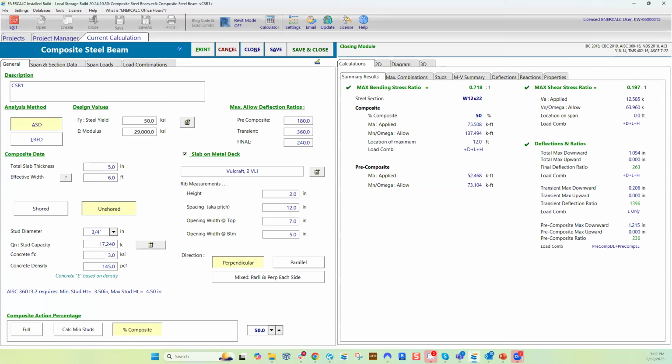All right. Question from Mark. Does the auto-calculated pre-composite slab weight include extra weight to account for the pre-composite deflection? No. Any additional concrete required to deal with ponding effects or the deflection would need to be accounted for as an additional pre-composite load. So the total pre-composite load that's being applied is just what you've applied in terms of the self-weight of the beam and the dead loads.